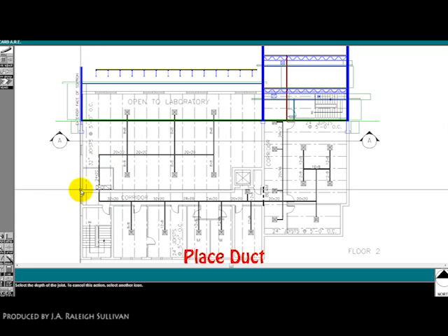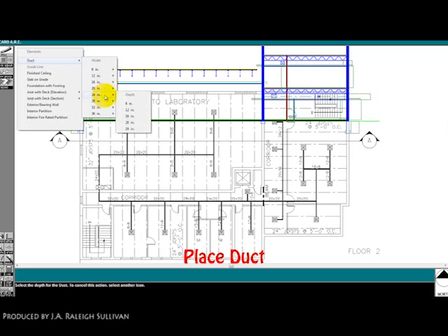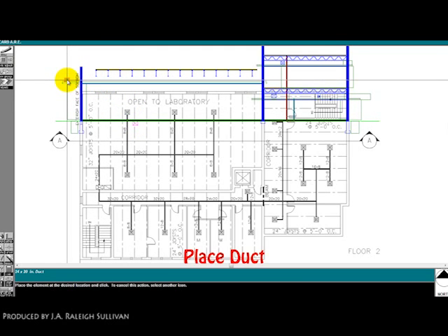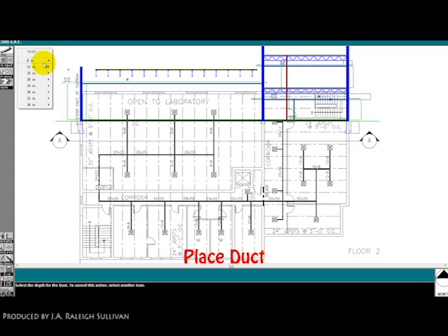All the others are smaller, but we have to provide room for that 24 by 20. So I'm just going to plop in the 24 by 20. That way I'm sure to get the right size. Over there. And while I'm at it, I'm going to go ahead and put in the actual ducts that our section is really cutting through, the 8 by 8s. I'm getting them aligned using these crosshairs too. We'll come back and adjust them later, but I know that it can't go into the light space, and I have a pretty good idea of where the joists are going to be, so I'm getting it close. But now we'll zoom in and really get these things fine-tuned.